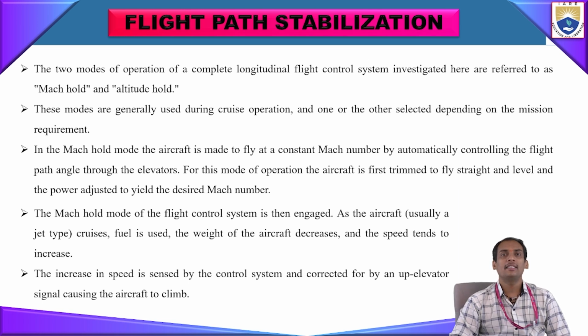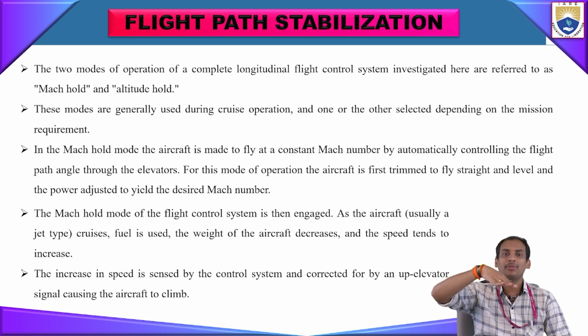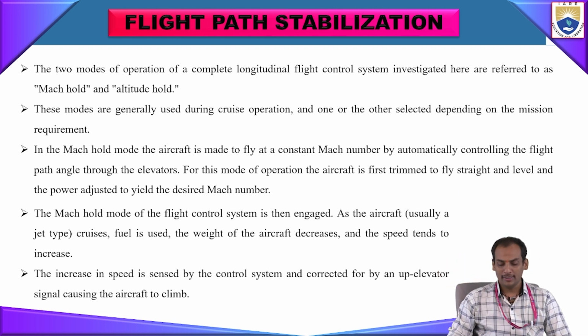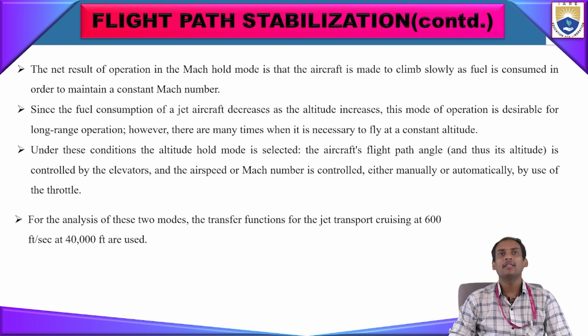The increase in speed is sensed by the control system and corrected by an up elevator signal, causing the aircraft to climb. For an elevator, if you give a pitching moment, the elevator needs to go up so that it gets the desired pitching angle. The net result of operation in Mach hold mode is that the aircraft is made to climb